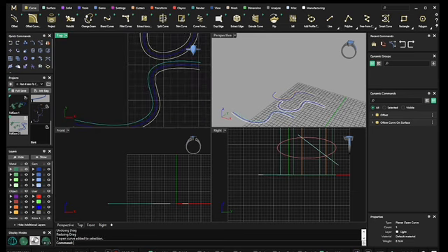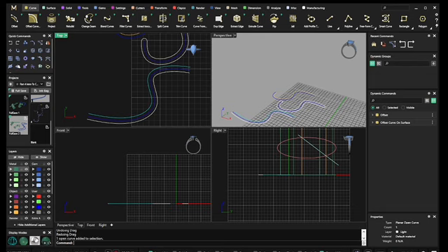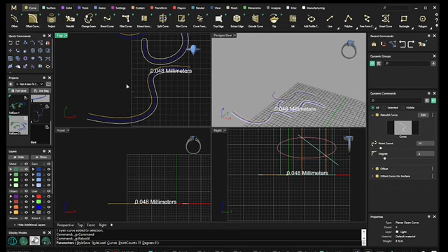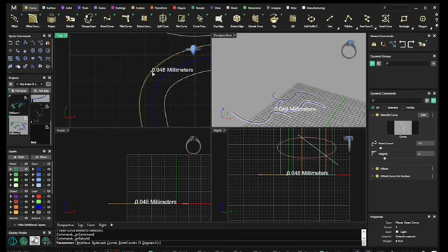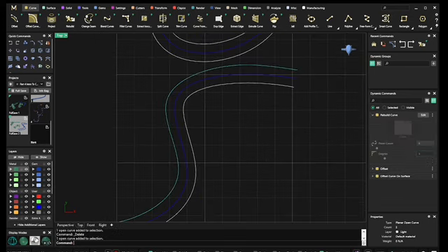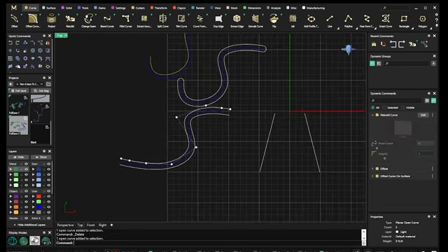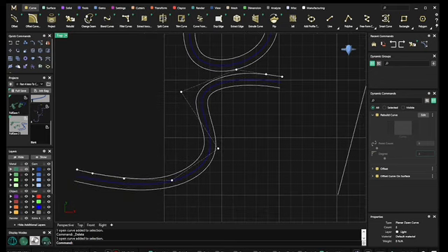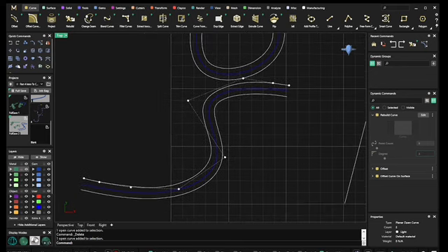So sometimes what I'll do is I will select that curve and I will hit Rebuild. Let's see, point count is 15. Let's change it to 9. And it usually gives you a preview, and I do believe that it, let's see if I got the right one. Yes. So now it is changed to 9 points, and it's much easier to adjust that.